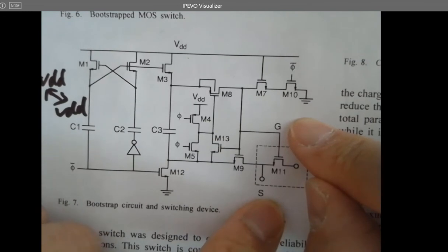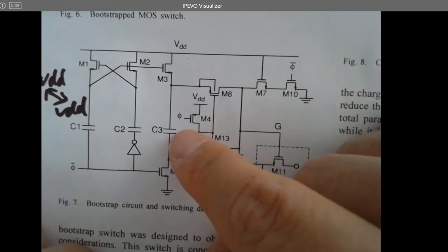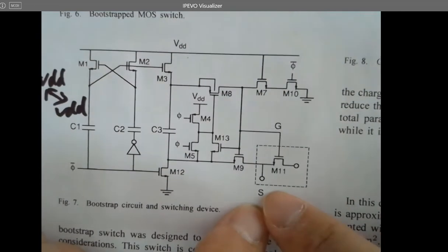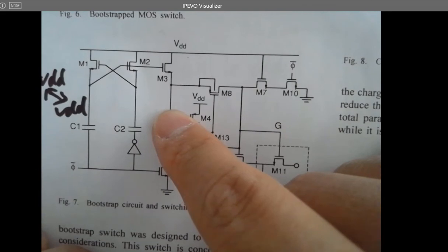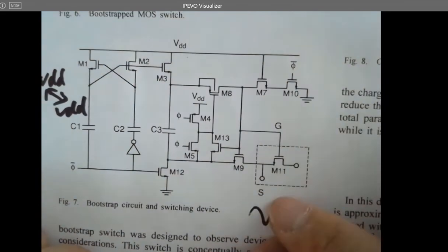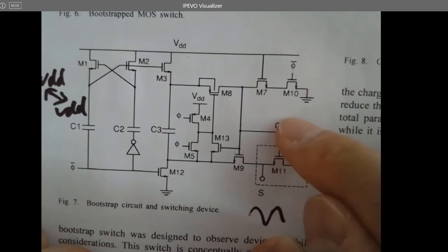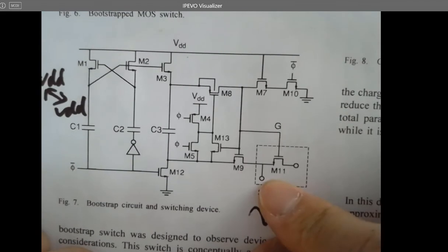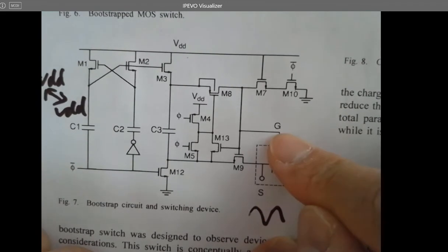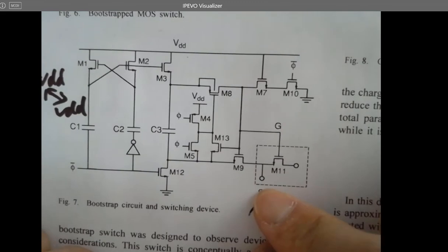It's constantly VDD because this capacitor is floating. And whenever VS is increasing, it's going to boost the signal as a charge pump to VDD plus VS. And VG is always VDD plus VS as well. So this minus this, VG is VDD plus VS, and this is VS. So VDD plus VS minus VS will be VDD constantly. It's not changing anymore.